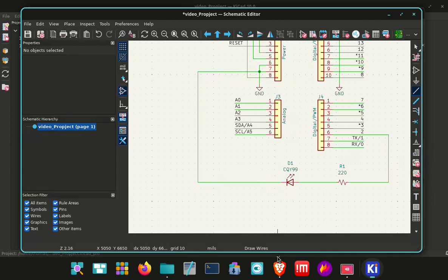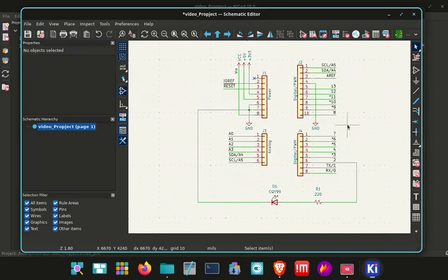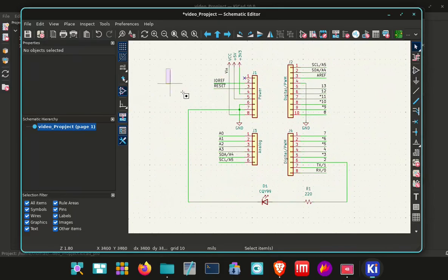It will find you a good route. That's nice and clear to understand. Otherwise, just left click a little bit, pull it out, left click, and it'll auto route from that point. So anyway, that's all good. I'm just going to try and come out of line mode. There we go. It's no longer in line mode, and I can do things like that and just select, right?